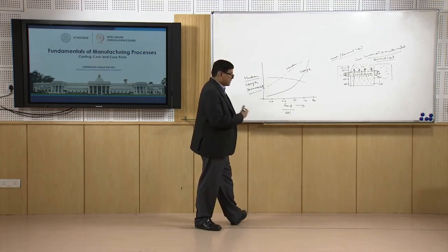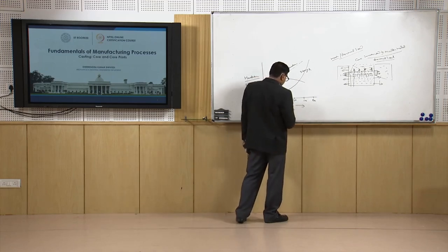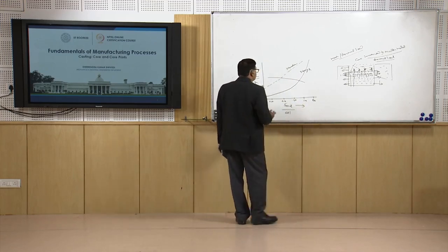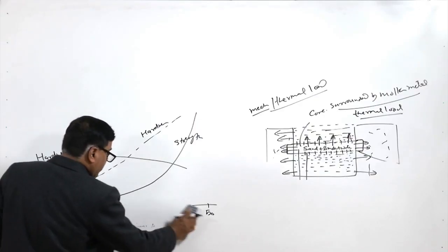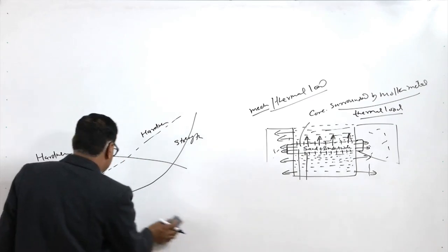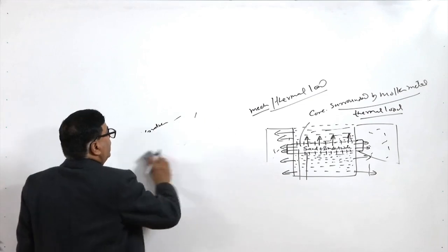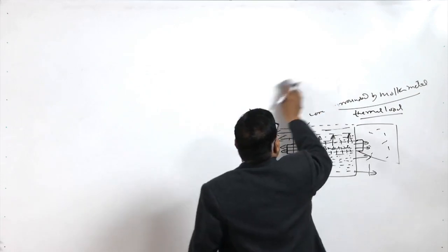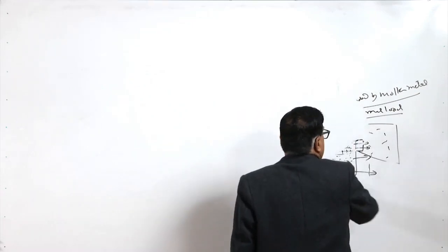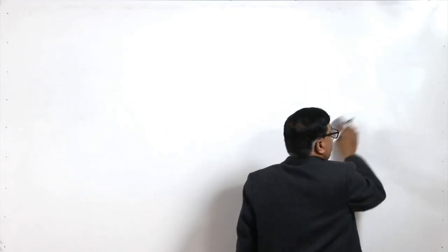With the increase in the fraction of oil, or you can say reducing the fraction of sand, that is the sand to binder ratio. So, as per the requirement of strength, permeability and hardness, the suitable ratio of sand and oil can be used in order to have the properties which are desired in the core for the desired purpose of strength and hardness.